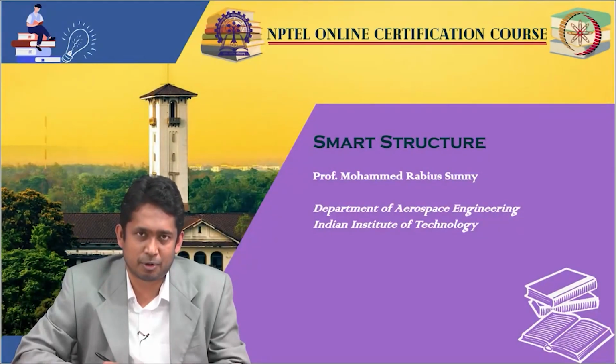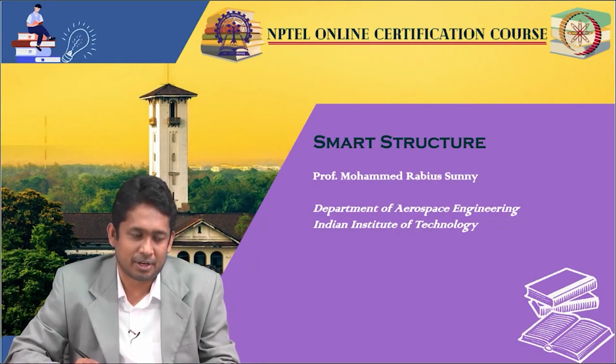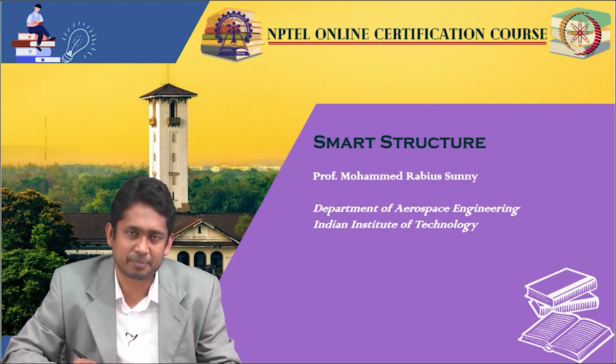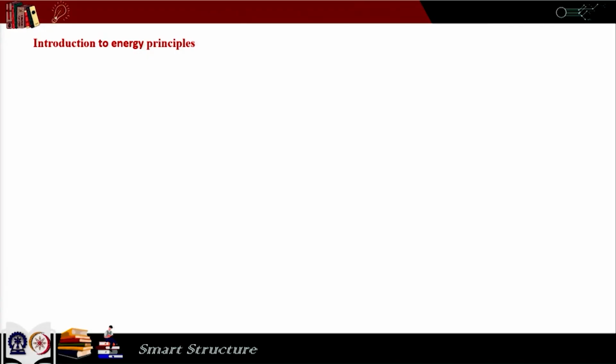Today we are going to start a new topic, that is on energy based analysis of structures with piezoelectric patches. Now, so far we have seen how to analyze these structures when we have the governing differential equation and we solve those equations. But most of the times such kind of solutions are very difficult, because it is difficult to derive those equations in many times, and even if we can derive those equations, it is